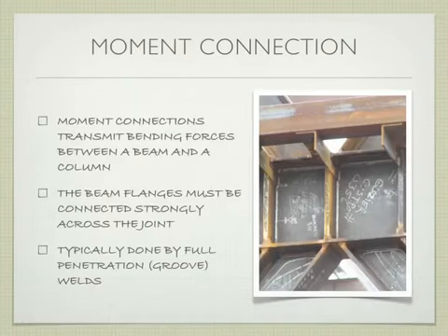Moment connections, which all of you architects, especially those of you in 220 that are talking skyscraper stuff, you need to think about moment connections right now, okay? Because moment connections transmit bending forces, so earthquake, lateral forces, from a column or from a beam into a column. They don't require any special braces. It's the strength of the weld itself that allows you to transition those forces.